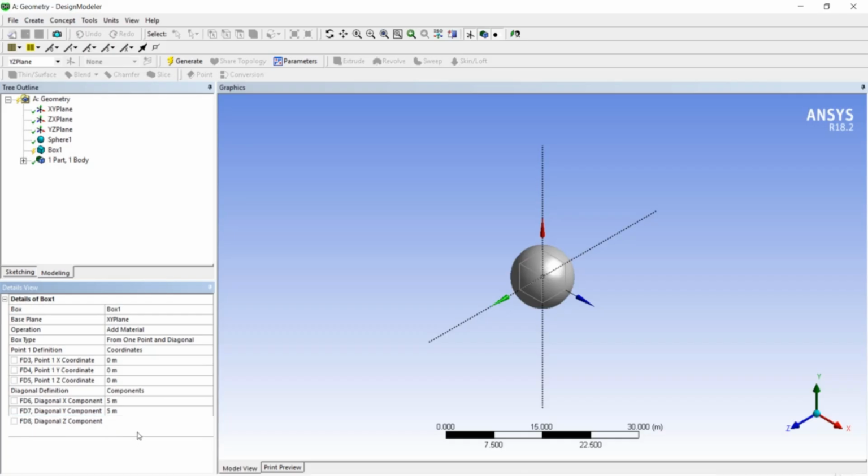In this option you can click here and select S. Then you need to give the thickness. You can give thickness in two directions: one is the inner direction and the other is the outer direction. Inner direction means, suppose you take this as the surface of the body, if you specify the inner thickness, what happens?